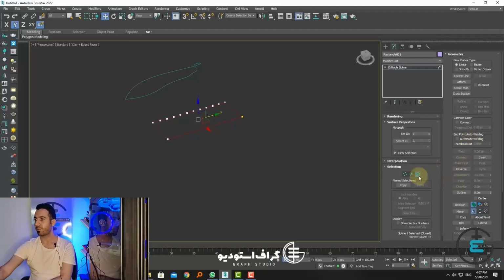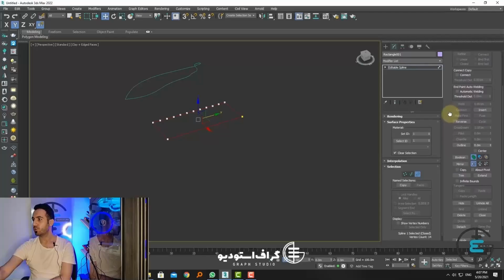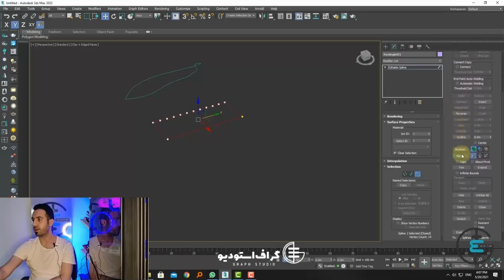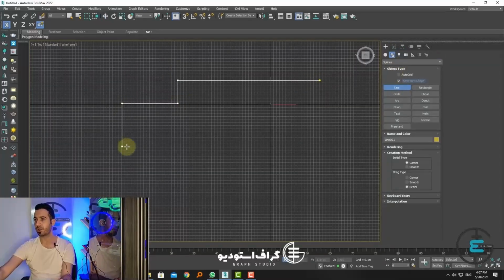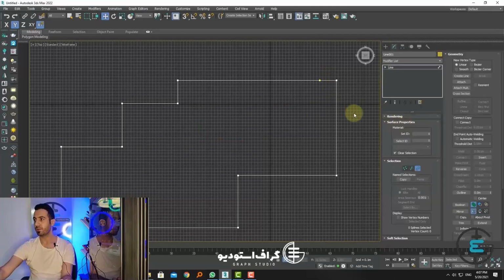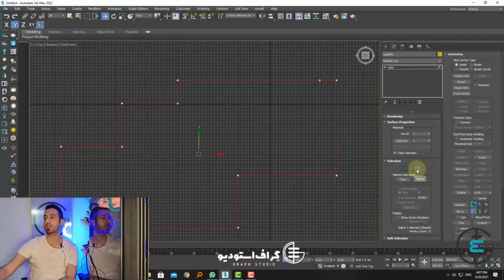After all, it doesn't become a single line. So you can see here, this point that was here, guys, you see that it was also applied in that outer line. Refine, please: if you want to specify the places of the windows through Refine, please first apply Refine to it, and then give Outline, so that those nodes are applied in the other line, so that we can easily select these later. Because if we don't do this, our work will be more difficult later. With this Outline that I gave, after our work is finished, deactivate it. After I give Extrude to it, you see that in this way, for example, 3D and 2D plans of architecture are how easily usable.